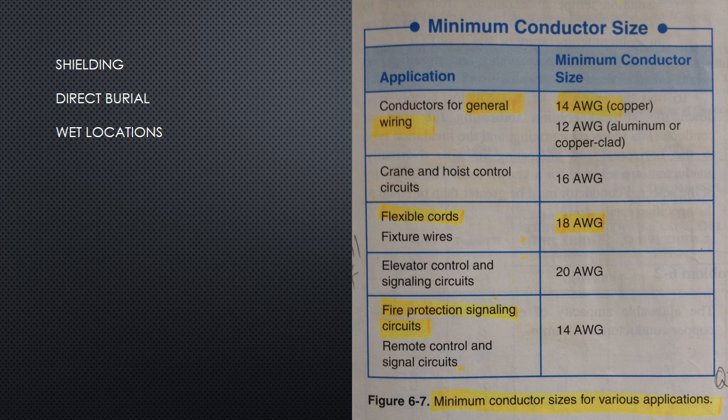Section 310.10(F) of the code states that conductors used in direct burial applications must be specifically approved for the purpose. In addition, these conductors, if rated above 2000 volts, must be shielded and the shield properly grounded. However, direct burial conductors rated between 2000 volts and 5000 volts do not require shielding if the cable has an overall metallic shield or armor.